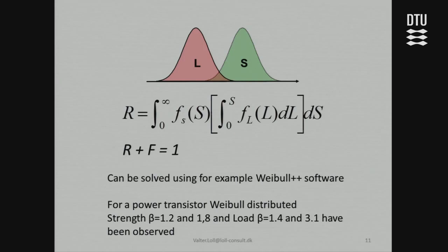You have the load spectrum here, and you can see that after some time of degradation and fatigue and corrosion, the strength curve will meet the load curve, and that is the end of useful life. So we can now take into account the wear out. Then my designer will ask, how much margin do I need here? Tell me how much margin is enough.